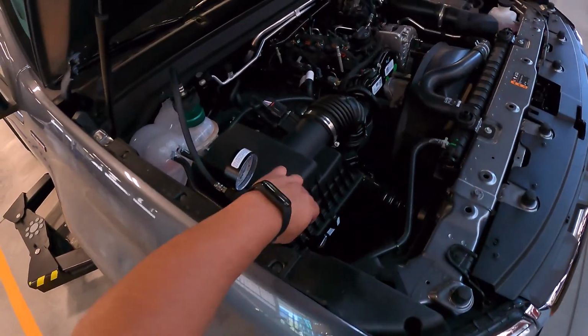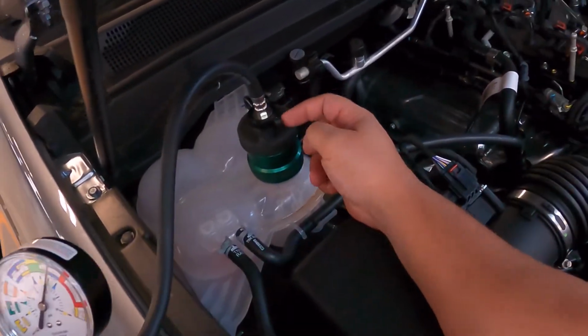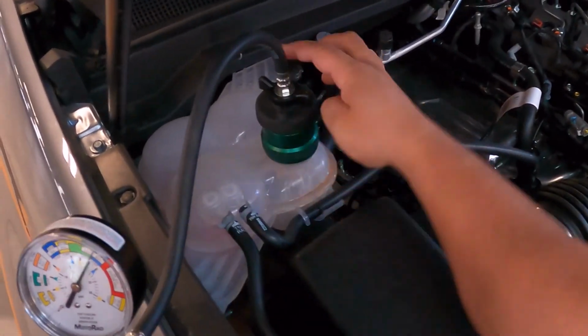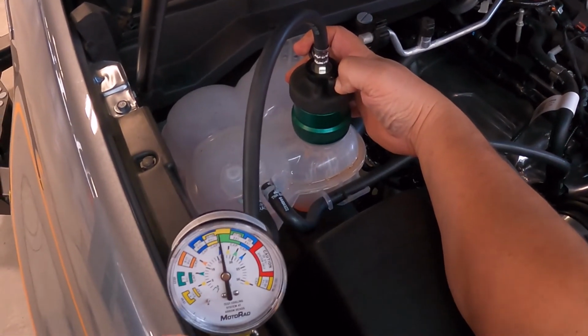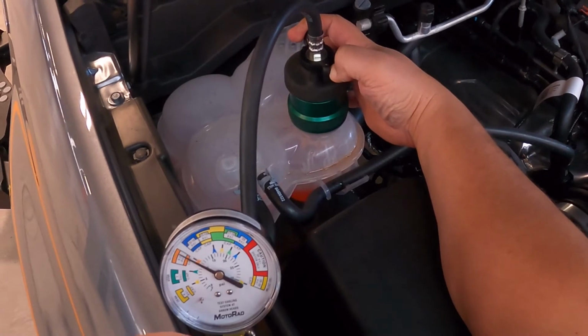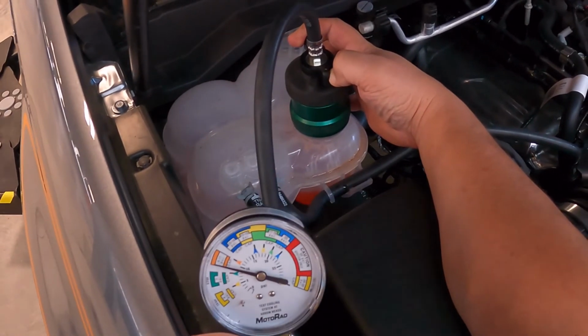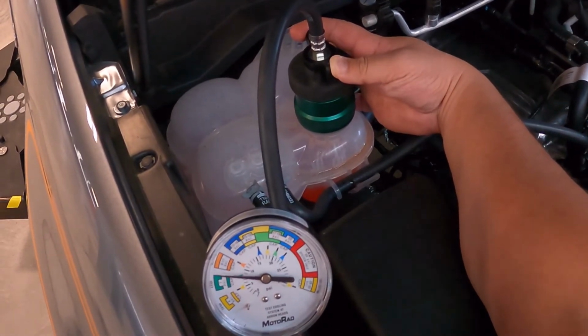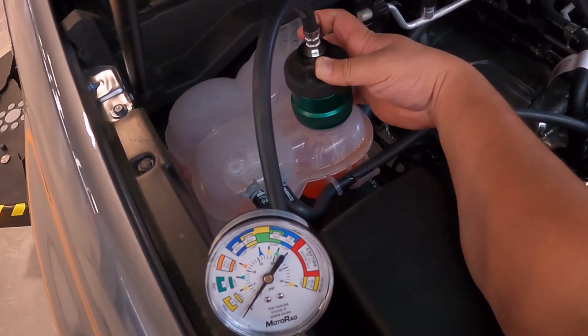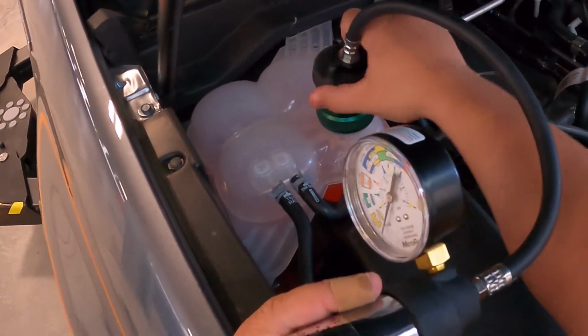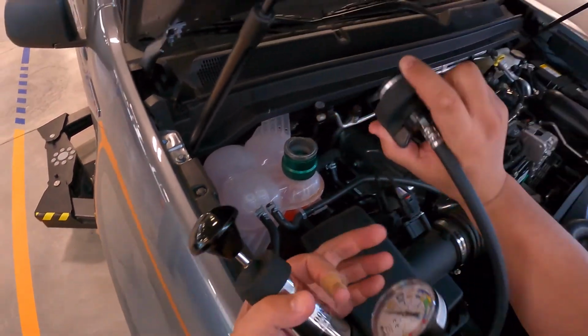From here, we need to remove the pressure tester. And to do this, you're going to very, very slowly turn that wing nut up to those ridges, and I mean slowly. Otherwise, this pressure is so high, it's going to blow all that coolant out of that tank. So turn that wing nut very, very carefully clockwise up into those ridges, and that way you will release the pressure and everything will be fine. So don't worry about it. Turn it slow, you'll be fine.